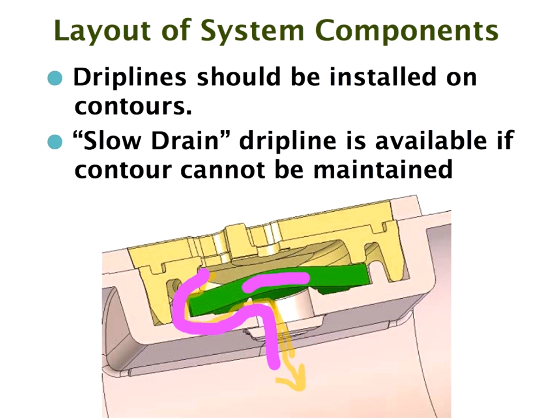And if you have circumstances where you have the sand problem, where you might be in very sandy circumstances, yes, I suggest you contact our office, Geoflow, or me, and we will certainly see that you get slow drain drippers for systems where you've got that risk.